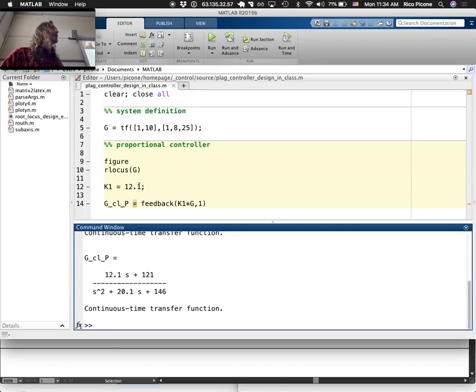If we increase the gain some more, we could also improve the settling time more. But we usually aim for just right at the cusp, because if you increase the gain more, typically you require more control effort. And more control effort means that you have to have bigger amplifiers and all that. So we tend to want to do a minimal amount of control effort if possible.